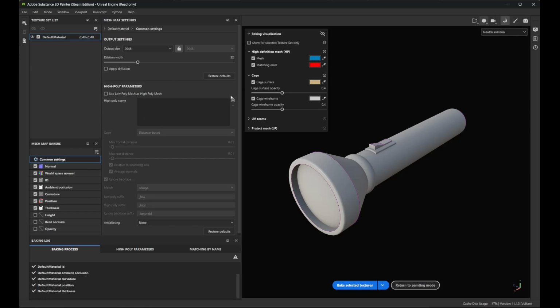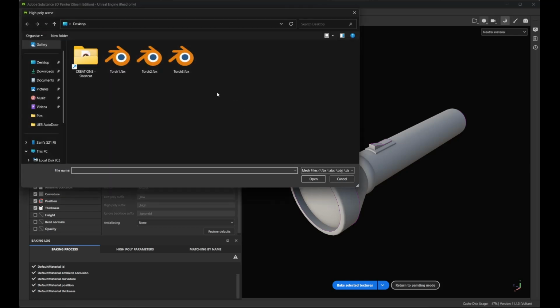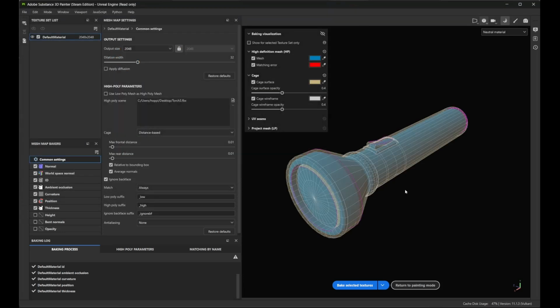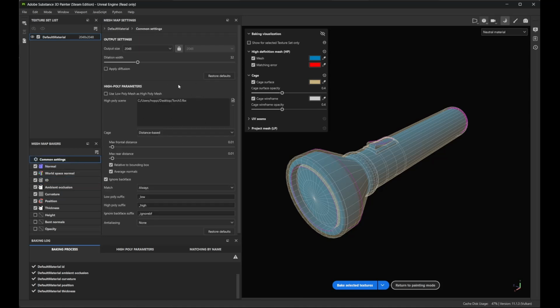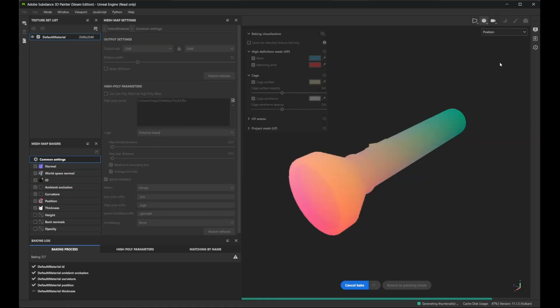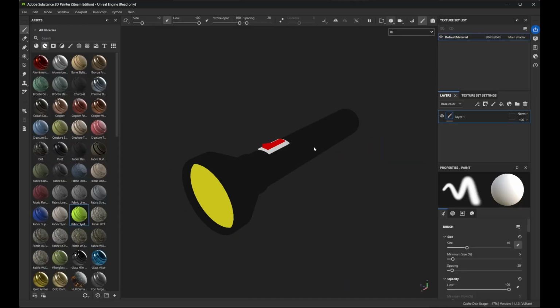So if you click this tiny little button, why is this button so small? No idea. Click this button here and find your mesh with all of the colors and materials applied to it, and make sure that the ID mask section of your mesh parameters is set to material color, and then we can generate an ID mask based on the colors in this already material textured mesh, which should look something like this.